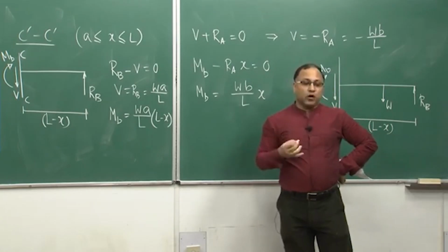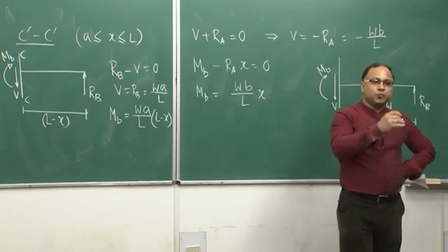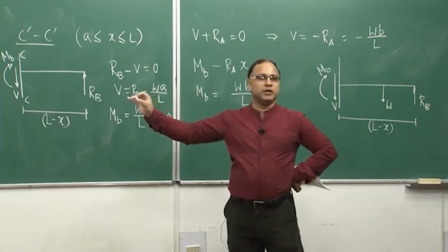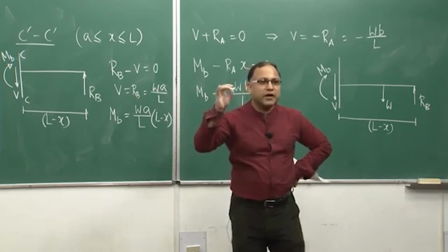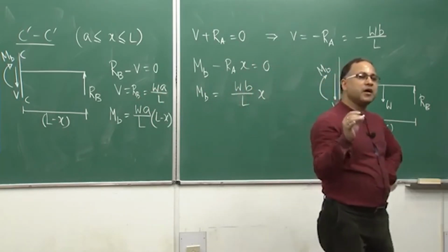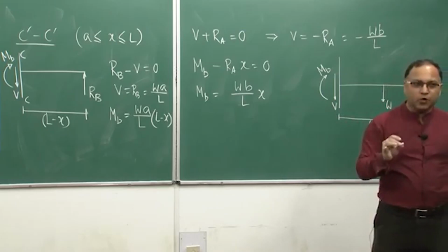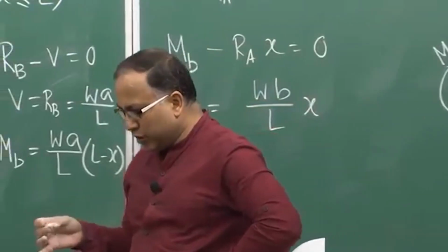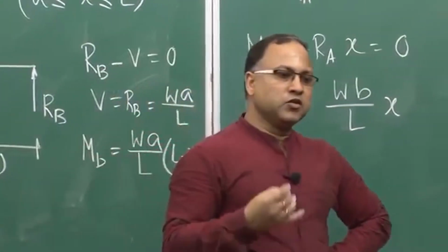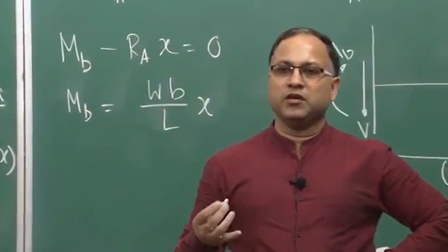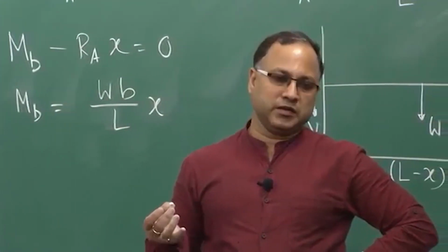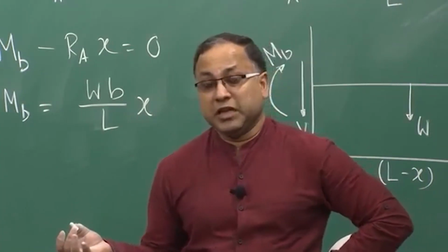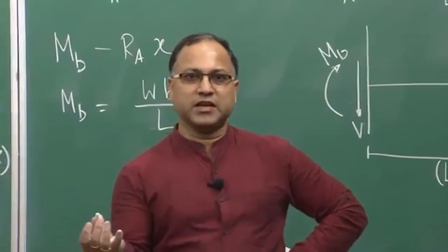So, therefore, what people do is try to plot the variation of bending moment and shear force along the whole beam or the slender member, and that variation is known as the bending moment diagram and shear force diagram. It is very, very important in mechanics, and if you are going to design something, this bending moment and shear force diagram will be very prime information for a design engineer, right.